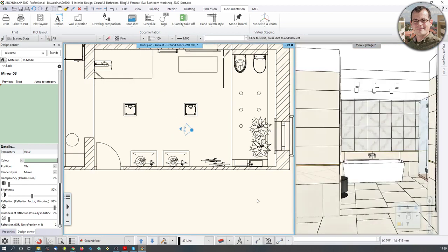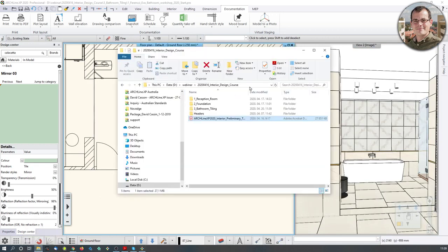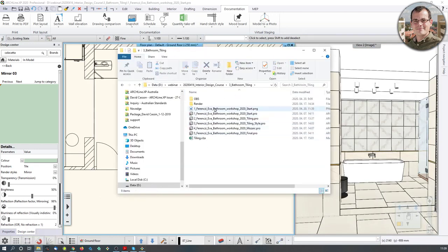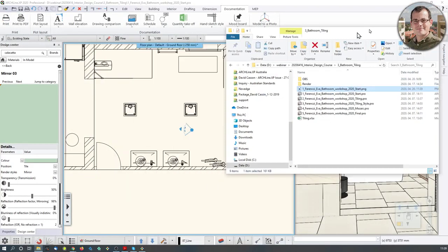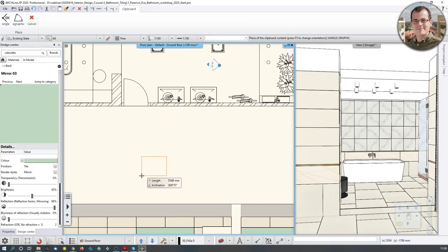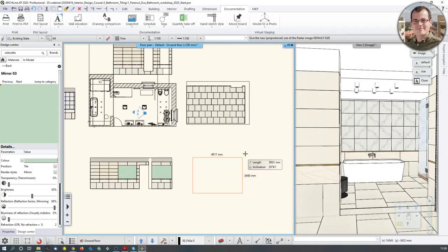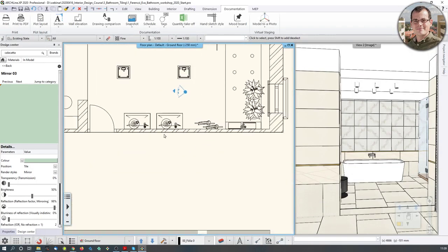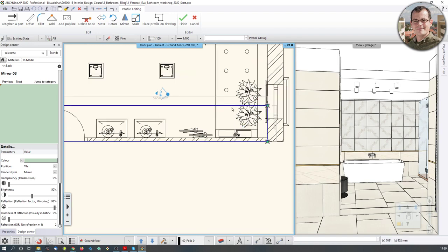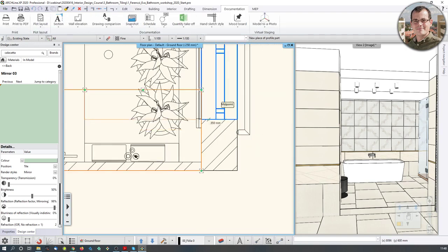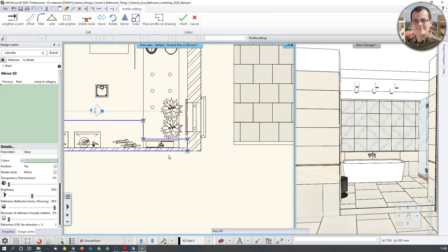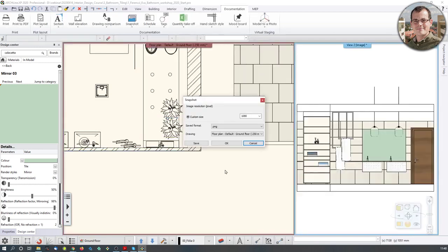And again, if you want to now get it into the design, then you go to the image that you have created and just drag and drop it in. This is not going to be in scale, so the better way to do it is to actually create a wall elevation image, viewing direction. Again, I have no problems with these plans, I just don't want to show them on the floor plan right now. So I'm in the wall elevation now, so let me just hit OK.